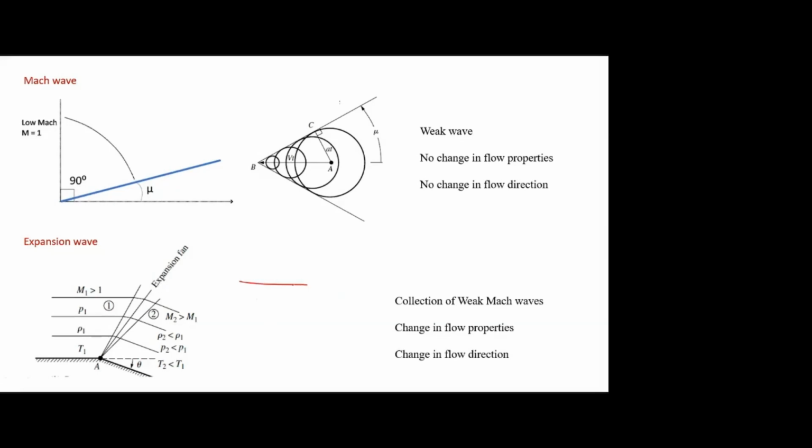And another thing, so this is the wall, and this is the supersonic flow, maybe Mach number 3, and actually it has to go straight, right? But see here there is a void, that means a low pressure region. So this low pressure region sucks the flow just above it, so that the flow is deflected and gets accelerated.